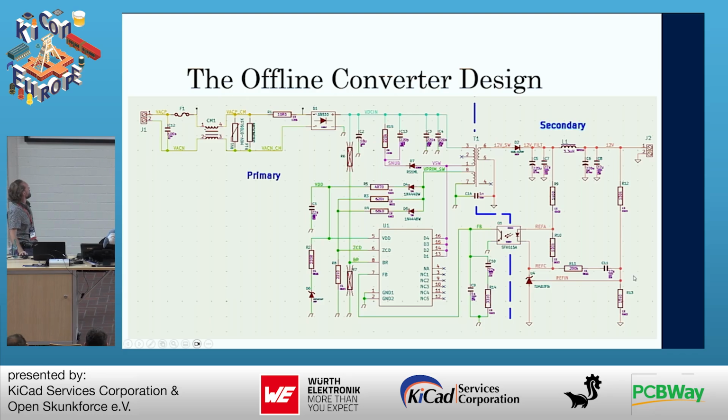And let's say we create a very large clearance as an isolation barrier and just said, okay, everything on the secondary side would get a huge clearance for those signals. Then they would also need a huge clearance to each other, which would make the secondary side huge. And you don't really want that, because there's no requirement for them between each other to have a large clearance. They can just use the generic minimum clearance that is common for your manufacturer, but you still want a large clearance to all the things on the primary side. And the same thing can kind of be said for some of the high voltage stuff.